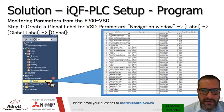So in other words, I will switch on bit M11 for the PLC to start the VSD going forward, and I will write to D112 in order to change its speed. And then you can monitor your parameters all the way from your torque down to your overload relay. This is just an example. You can monitor all the parameters if you want, depending on how you actually set up this program.